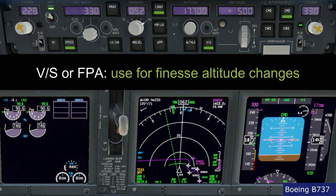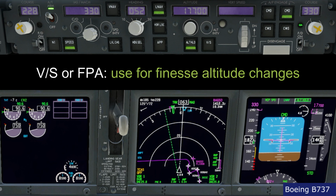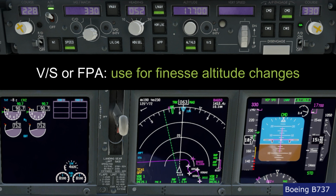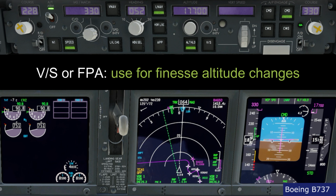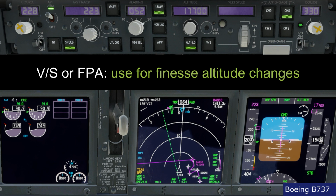So remember, VS for finesse. You will use VS only when you have to make smooth corrections and not such a large correction. Okay, so what I can do now is click Alt hold, and it's going to maintain the altitude at which I was. You see the aircraft is now rapidly decreasing the pitch, because otherwise I was about to stall. Now with Alt hold, of course, the speed is going to increase rapidly, because also in Alt hold the speed remains managed by the auto throttle, so the auto throttle remained in MCP speed.